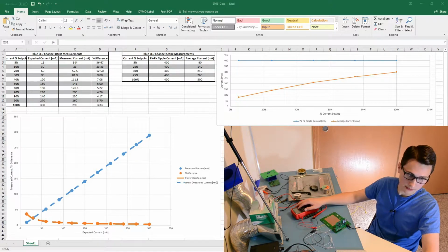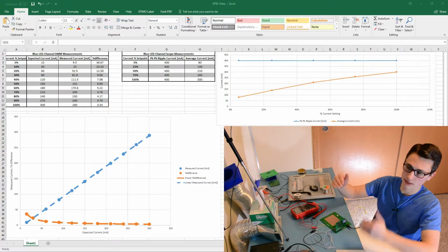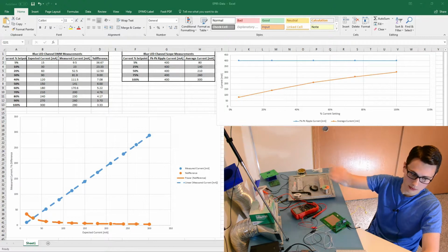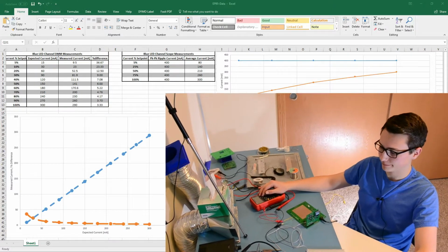That said, now that we've characterized this lamp, we can modify our PWM equation that converts from a current set point to the PWM value to send out to the hardware. And we can take this data and compensate the algorithm so that we will get approximately 0% difference from 0 to 100% of the range using a piecewise or more complicated function.